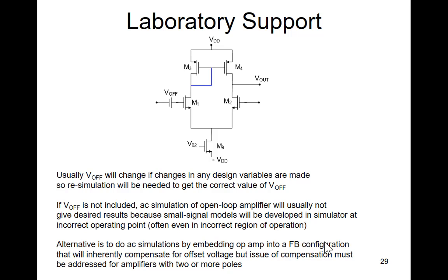Yeah. Does Cadence have, so that's in Spectre, right? Does Cadence have another simulation tool in there that maybe piecewises it out and generates a new simulation circuit for that type of test? You have to do a time domain input. You can't do an AC sweep. So you have to do a time domain input, and then you can calculate the spectral characteristics. You can only do a post analysis then. You have to take your transient data and put it somewhere else. That's correct. Gotcha.